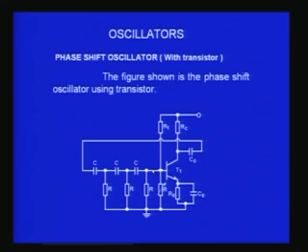I will explain to you how this happens. Therefore this becomes the input voltage, and if the conditions are ideal, then this input will get amplified just enough, so that after passing through the 3 RC sections it again becomes the same value as the initial value. So you get a constant input voltage, and these 3 RC sections provide 180 degrees in addition to the 180 degrees produced by the RC coupled amplifier. The total of 360 degrees provides the necessary positive feedback, and therefore if you now take another wire from here and connect it to an oscilloscope, you would find it will start oscillating.